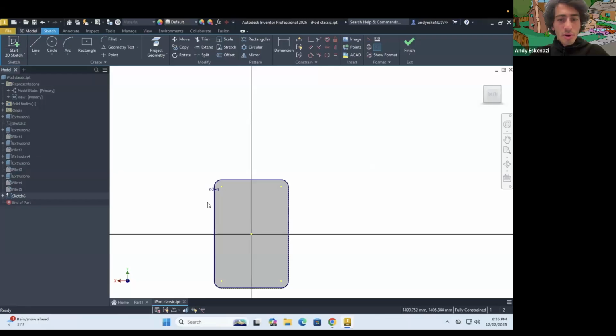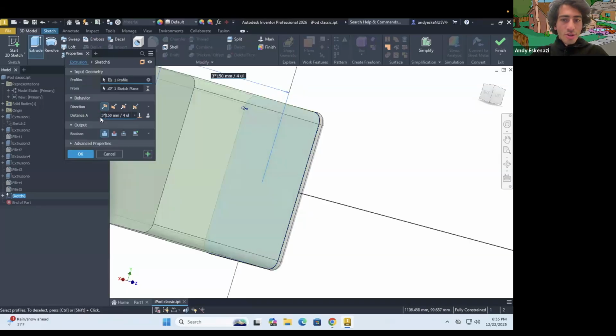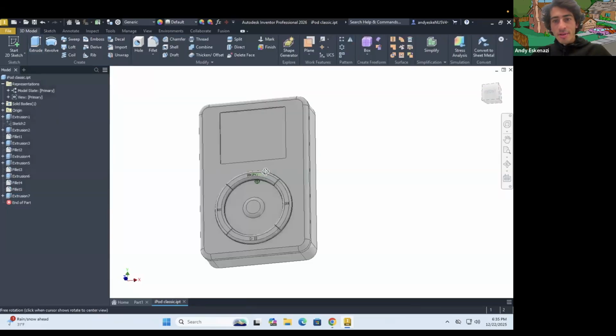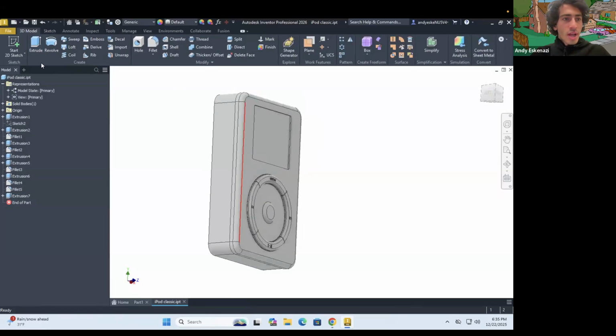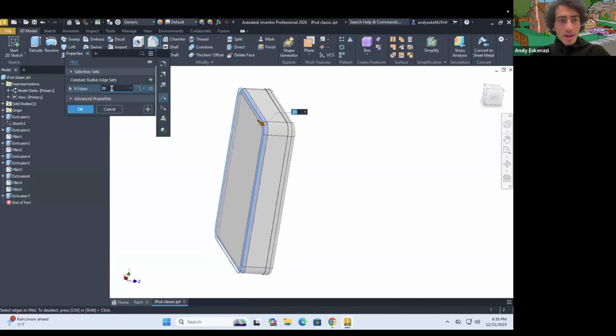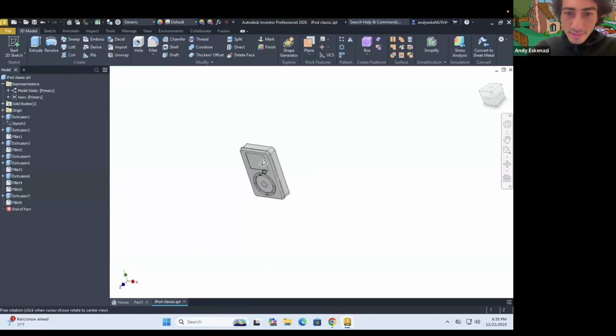Because now we'll hit here the 3D model, sketch, and we're going to bring that out by 100. So I'll say 3 times. See how you can literally do math in here. Very good. So now we go here to fillet. I'm going to check that. I also give it 20 millimeters. So it's like a nice blocky thing.